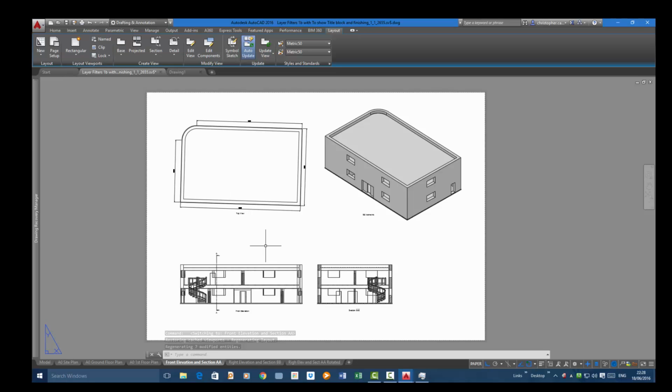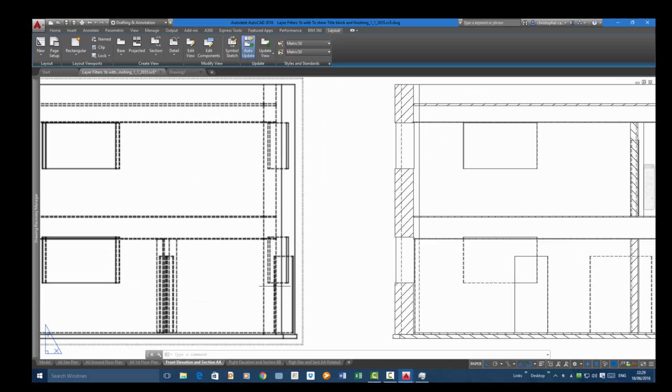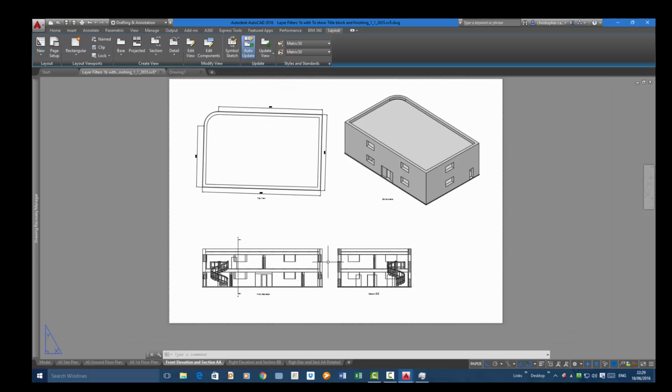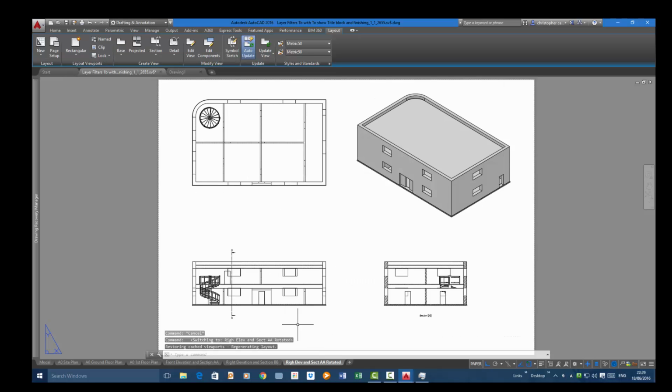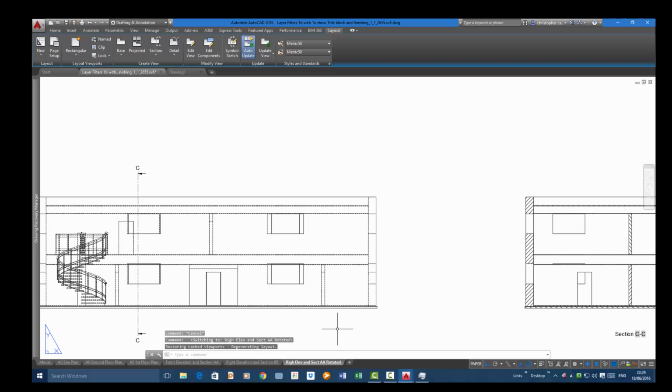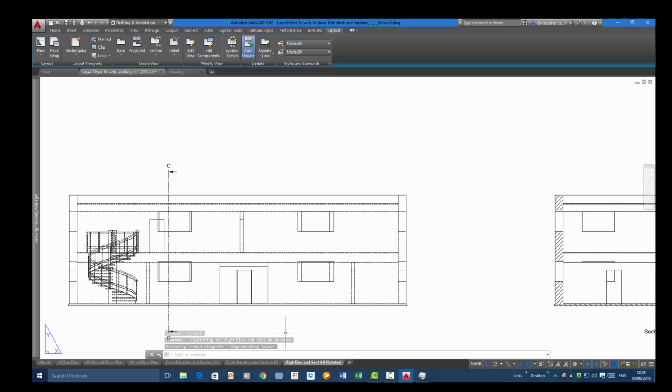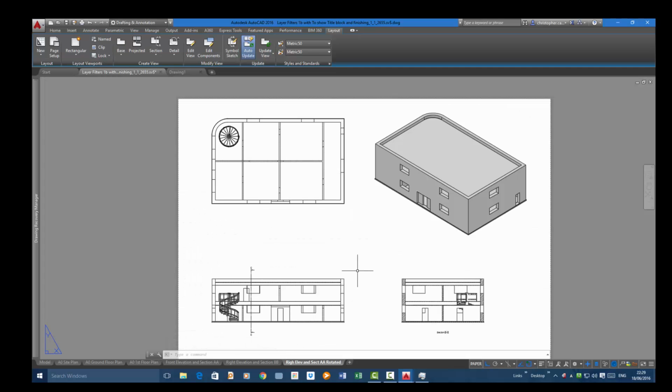The view is a little bit different on the top view there, but if you notice that where that's rotated and the front of the walls in hidden detail don't line up with the backs of the wall because the building is projected from this rotated view. On the straight view, you're looking at the building square on, and it appears as it should do.